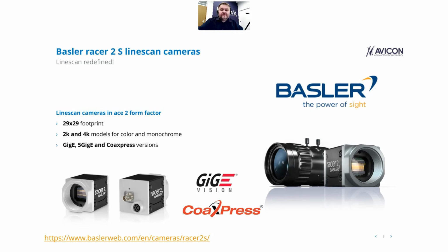So CoaXPress is a pretty non-standard interface for everyday computing. It needs some extensions to the PC. It doesn't work well with laptops, for instance. We need PCI Express extension cards. However, at this expense, we have a very good throughput, reaching up to 1.2 gigabytes per second of raw image data.